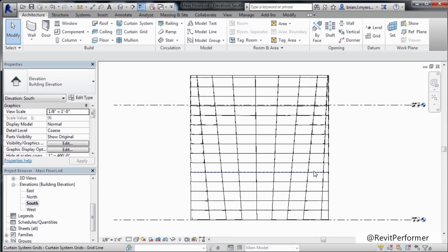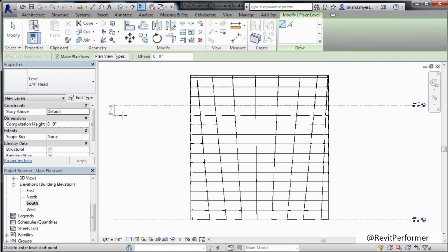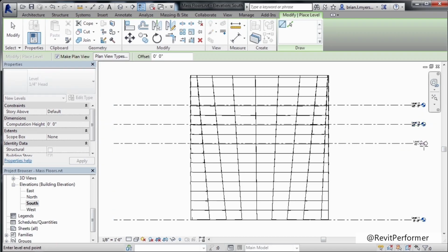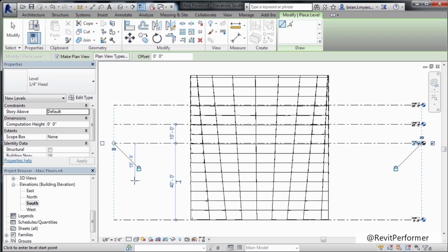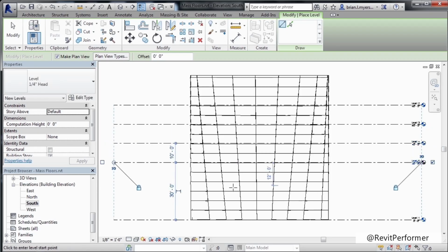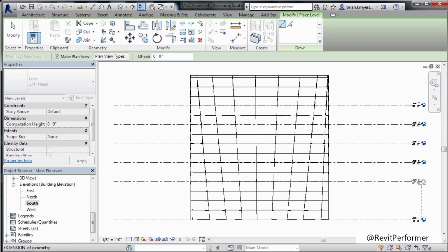What I'd like to do now is start to add levels to this building. So here where we have Architecture, click on Level. And about every 10 feet, let's add another level in. So come down here, click, and continue this process by adding in at least 2 more levels. You don't have to add in the exact same levels as me. You can actually have a unique building if you want. That's just fine. We'll come down here, I'll add 1 more level.